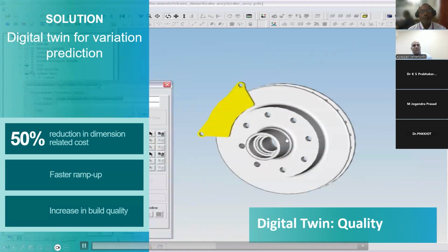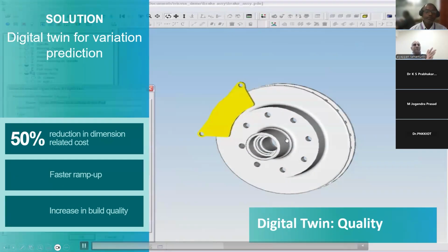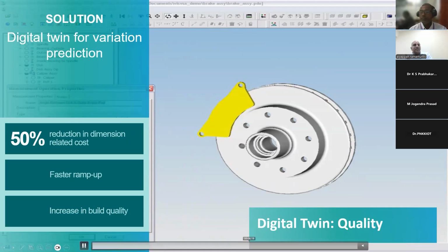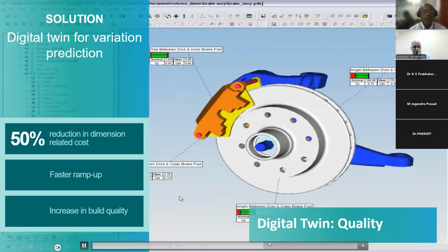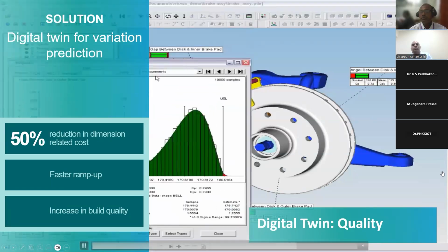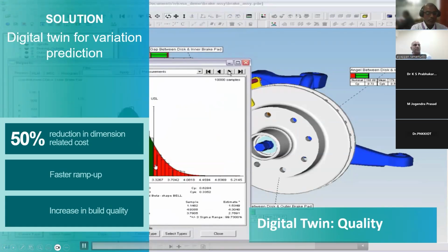And what is the primary operation? The primary operation becomes the base operation, and you create all other operations based on the primary operation, and then you have the jobs which are completed for machining, and then you take them for assembly. Now you can also do a virtual assembly, and this gives you the ability to look at how well the production is going to happen.